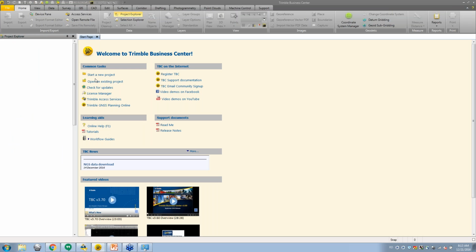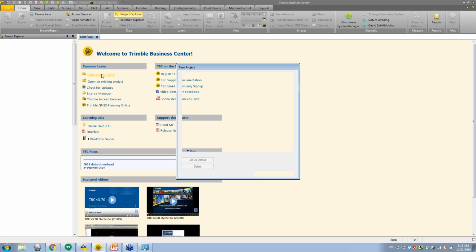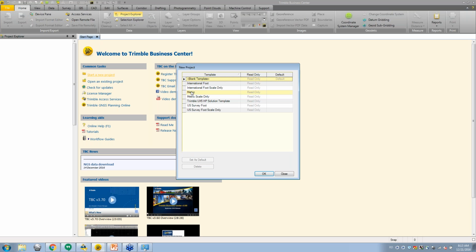All right, thank you, Riley. We were going to start with actually showing you the Trimble UAS workflow, but we found out we don't really have that much time, and hopefully we're going to be moving through this fairly quickly. It should be very elementary, or at least the simplest workflow we can provide you, and hopefully everyone can follow along. So your first step is to start a project like any TBC project. Set the units. We'll be working in metric today, and then as is always good practice, we're going to want to save this project.